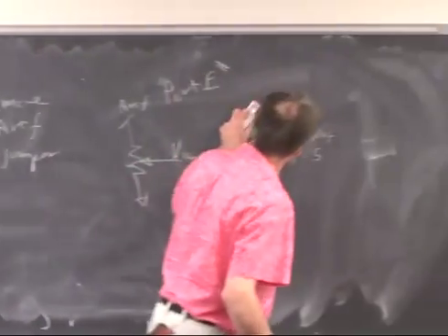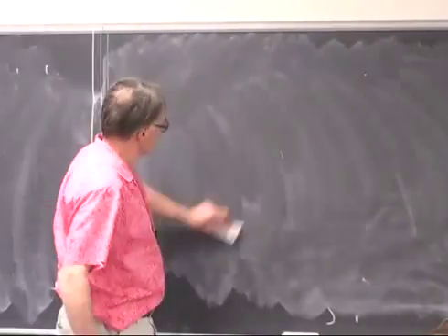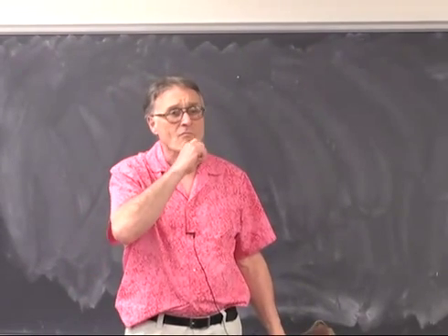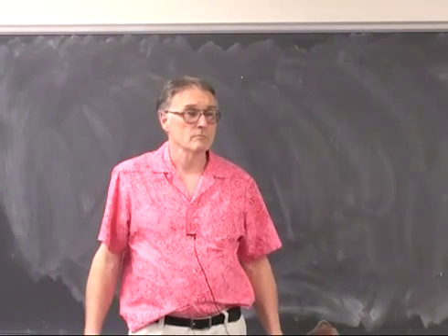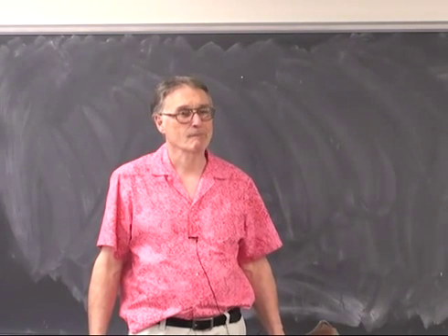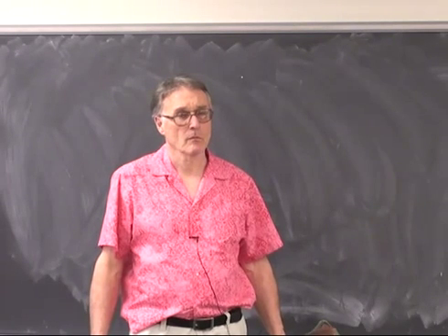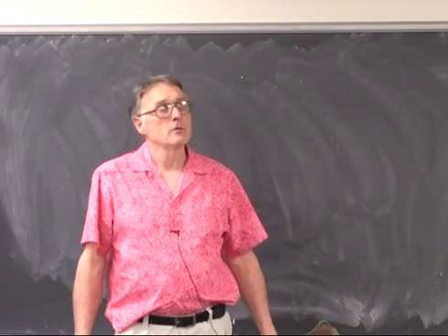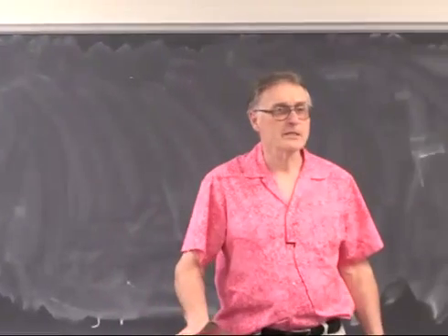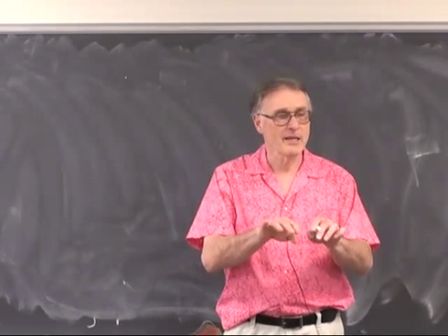Okay, now to keypad. It is not exactly 1.1 volts. So, how are we supposed to, do we need to pre-calibrate this? Like, we know that it's going to be 1.14 or something? So there's no way to get around that except to put a digital voltmeter onto the pin and measure AREF and then type that into your code.